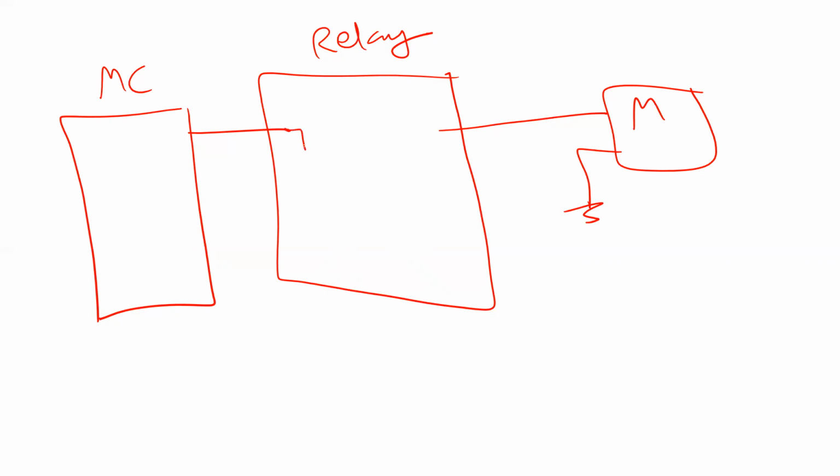The main idea is that here there is a coil. You know coil, right? When this coil is energized, so when you put here 5 volt, you energize the coil, and when you energize the coil, you actually turn the coil into a magnet. Then there is a switch here, a physical switch, and it has something like a spring here.